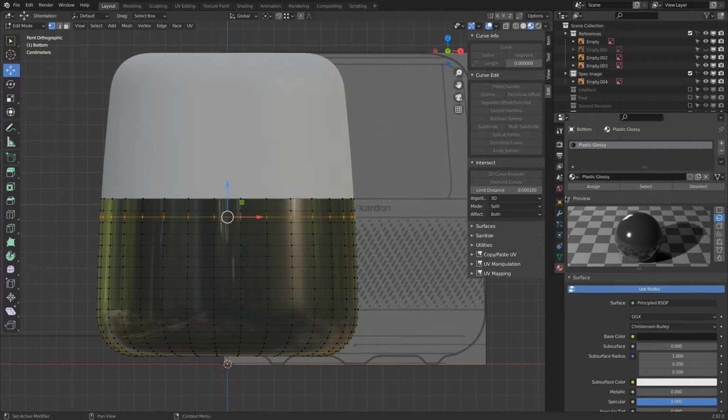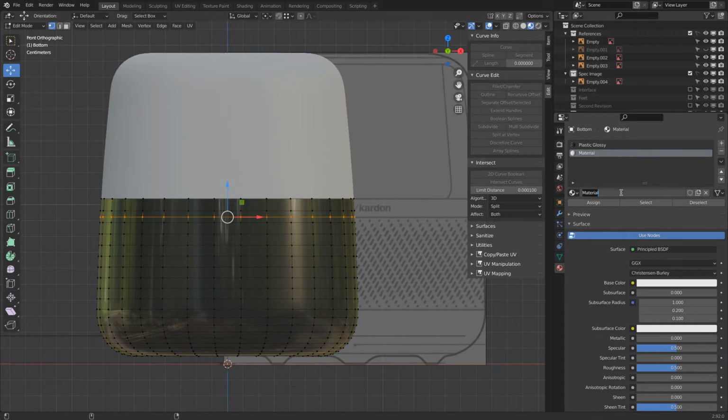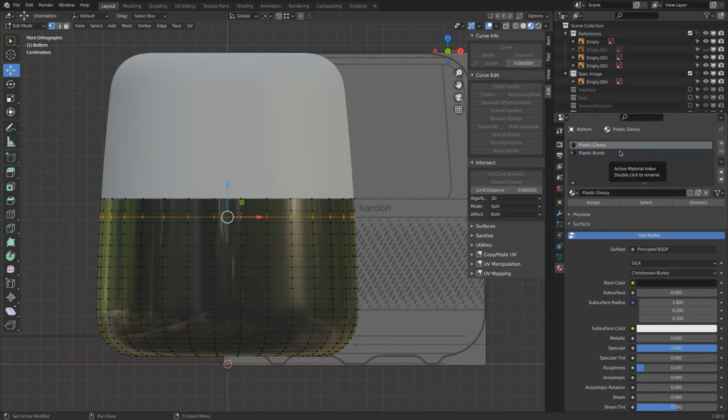Now we would like to make a new material. So click and then New, and we call this one Plastic Bump. Here we could Control C on the black color, go to here, Control V, paste this in. Roughness 0.3 for the moment. Reflectivity actually 0.4 maybe. Again, I'm playing with extremes, so visually it's very easy to see. But right now we don't really see anything happening.